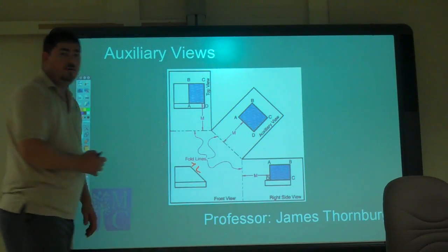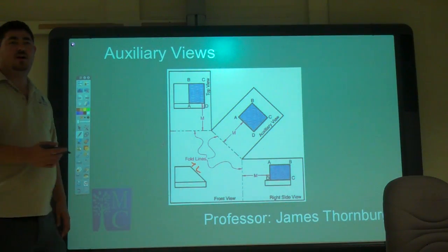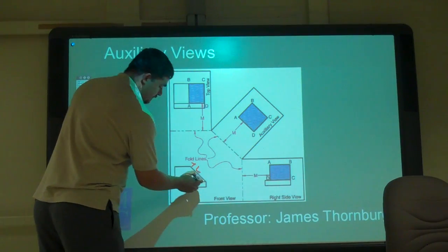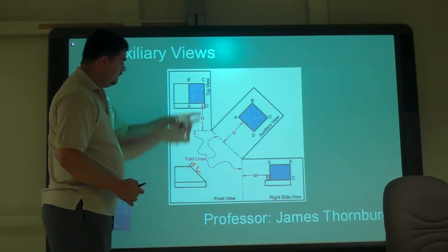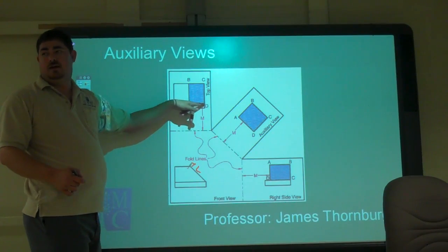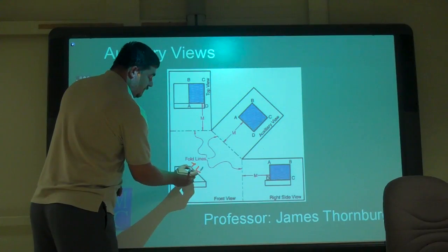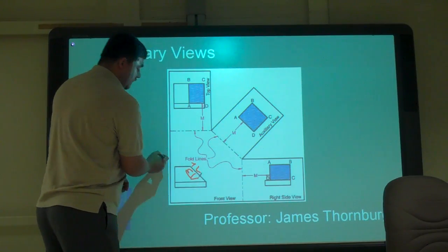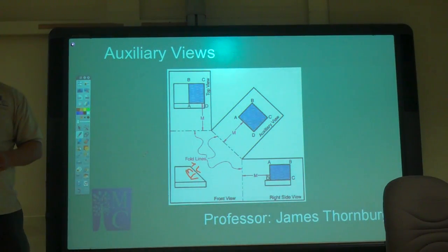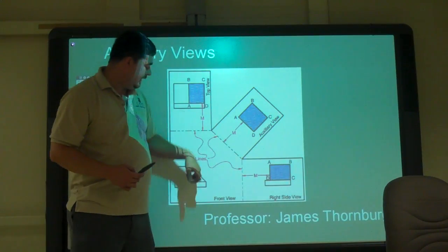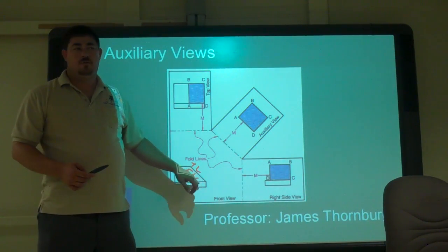That's true length there. And it's also an edge view, right? So I can see that whole surface as an edge. And so this line here is true length. And the whole surface is an edge view with that line, right? You guys agree? Oh, so the whole blue area is green. Yeah, that whole blue is that plane right there. Yeah, so it's true length.